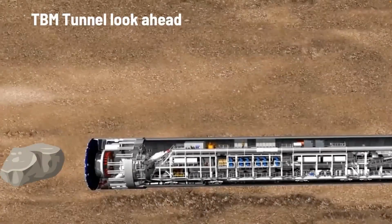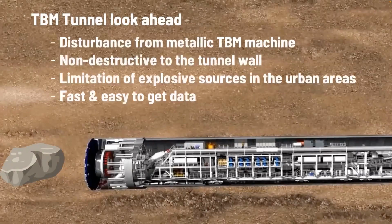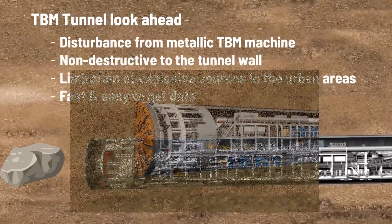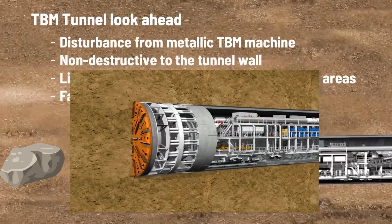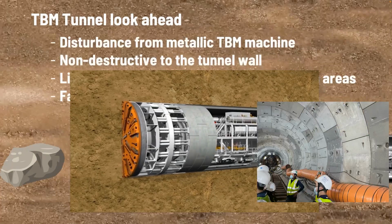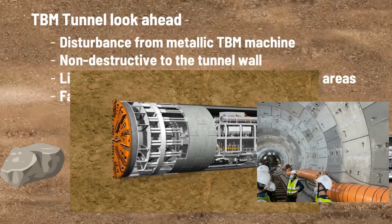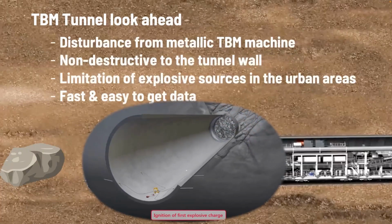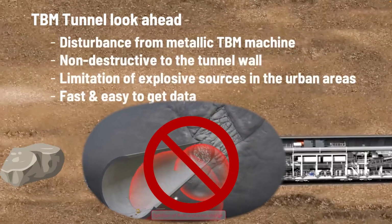For the TBM tunnel look ahead, as the existence of the TBM machine, we have some limitations and requirements when designing a look ahead system. At first, the metallic TBM's disturbance limits the use of electromagnetic waves to detect. And in the TBM tunnel, the tunnel lining with segment rings behind the TBM is built just after the mining, so we need a method that is non-destructive to the built terrain. And thirdly, as a limitation of explosive sources in urban areas, we can't use any explosive sources.